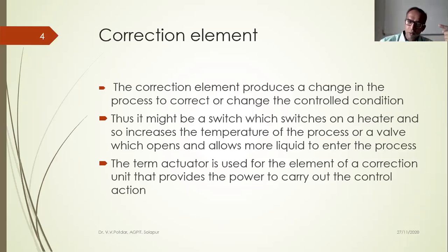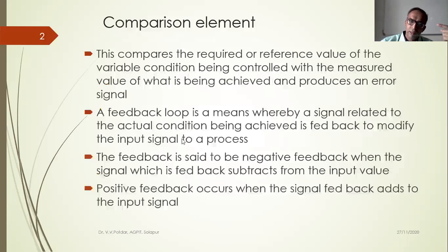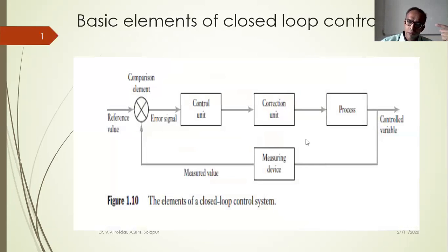Now this set value is 16 volt, and what is the actual value is 1500 degrees Celsius is the present value of the temperature. So 15 volt, it will be feedback signal will be generated, and that will be compared with my set value of 16 volt. So the error is set value minus feedback value, 16 minus 15, it is 1 volt. So that 1 volt signal will be suitably amplified. So it is plus 1 volt.